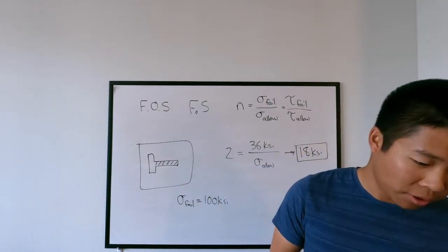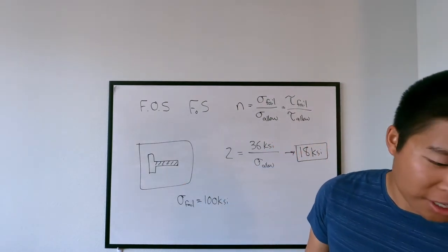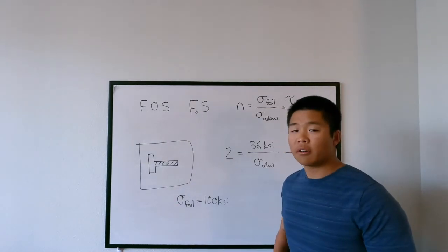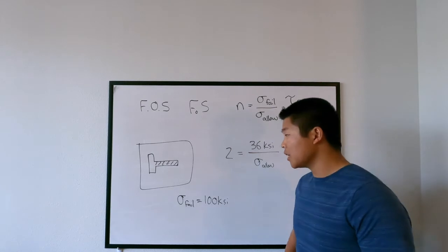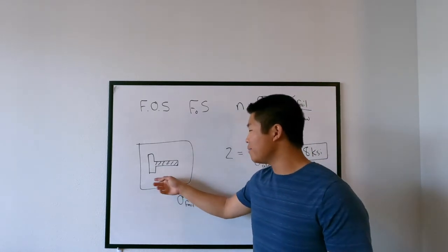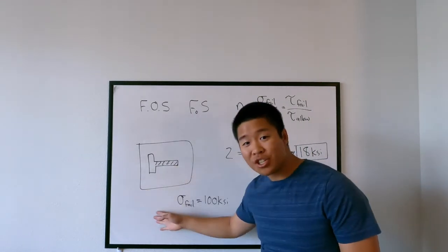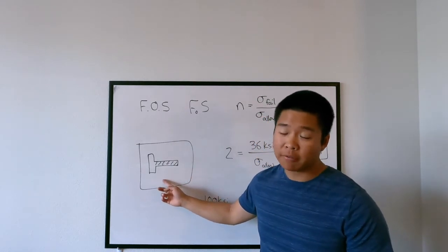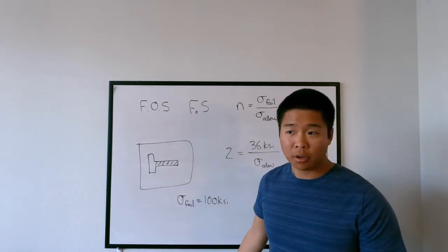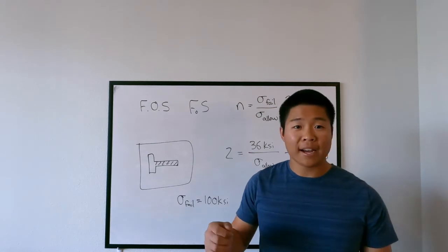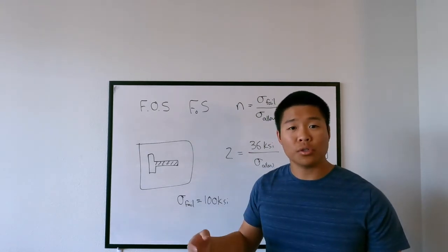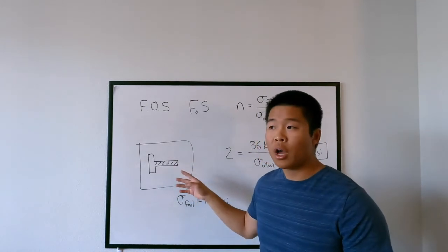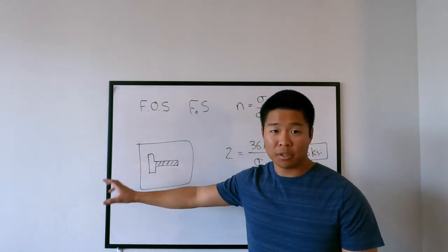For other things such as buildings and bridges, we don't really care too much about the weight, do we? So therefore, it's much cheaper. Think about it. If you had to buy a bolt with a certification on it, then you would expect this bolt to be a lot more expensive than just buying a bolt from Lowe's. So that's the reason why sometimes it's actually cheaper to use a higher factor of safety, because you don't need all the paperwork that comes along with certified materials.